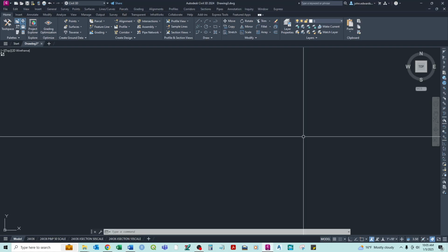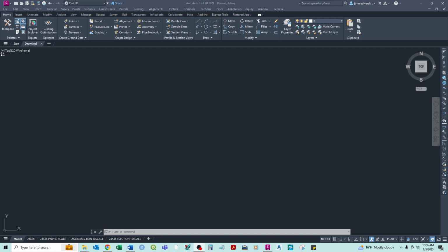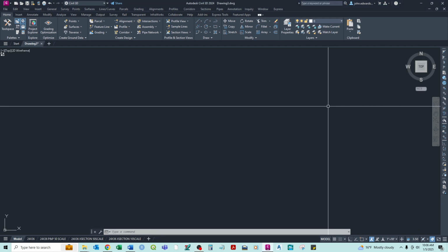Okay, this is, I think, the fourth video within our beginner AutoCAD series for drafting and design. In this one, we're going to build on the progress of the last couple of lessons and specifically talk about snapping and grip editing and how that relates to how we can move and tie into specific features. We're still going to be focusing mostly on lines, but by the end of this, we're going to move into polylines, which is an extension of basic line features.